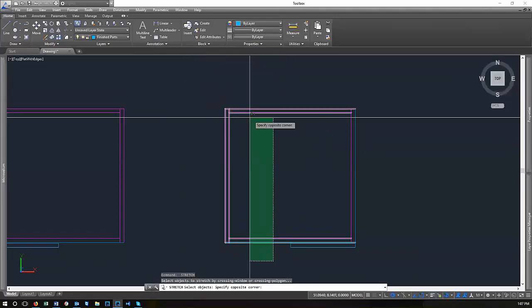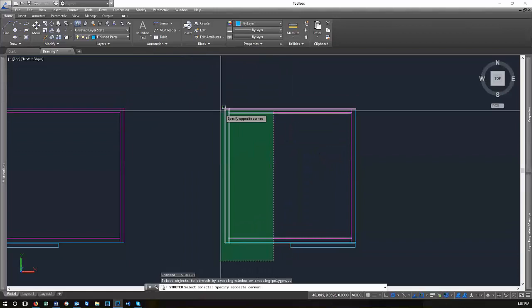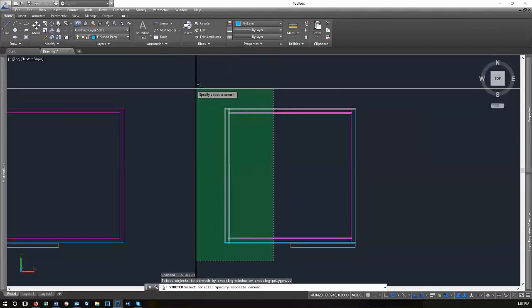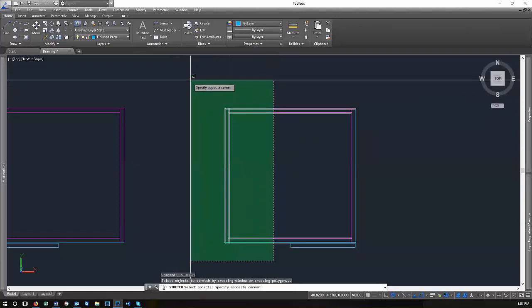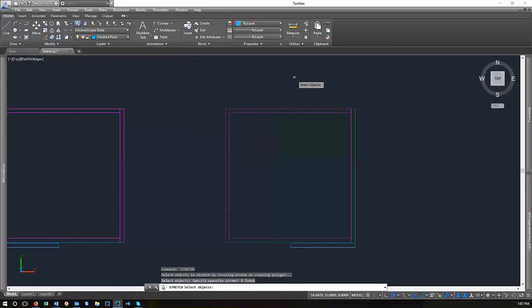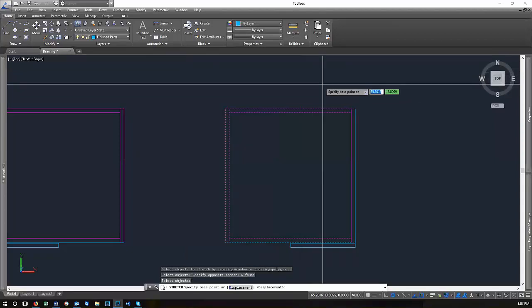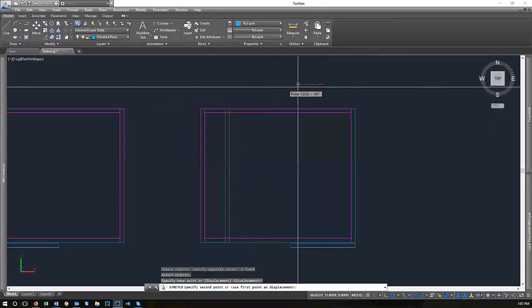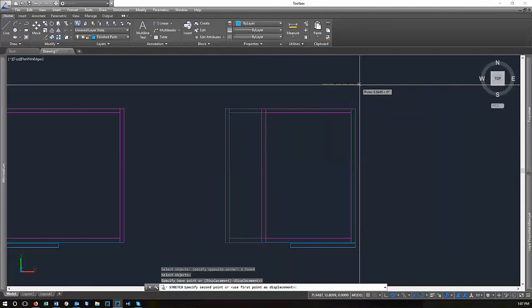Midpoints don't matter so much. Those aren't helping define these lines. They just show you where the midpoint is. But I'm windowing the endpoints or start points, depending on which you're talking about. I'm going to select, and I'm going to drag out, and that'll make it longer. Or I can stretch in, and it's going to make it shorter.